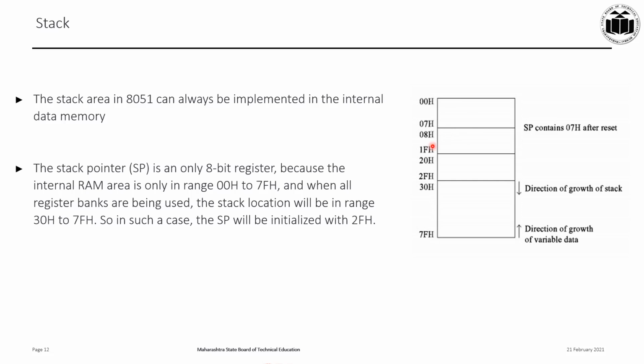But when all the register banks are being used, the stack location will be in the range of 30 hex to 7F hex, as you can see in the diagram. In that case, the stack pointer will be initialized at 2F hex.